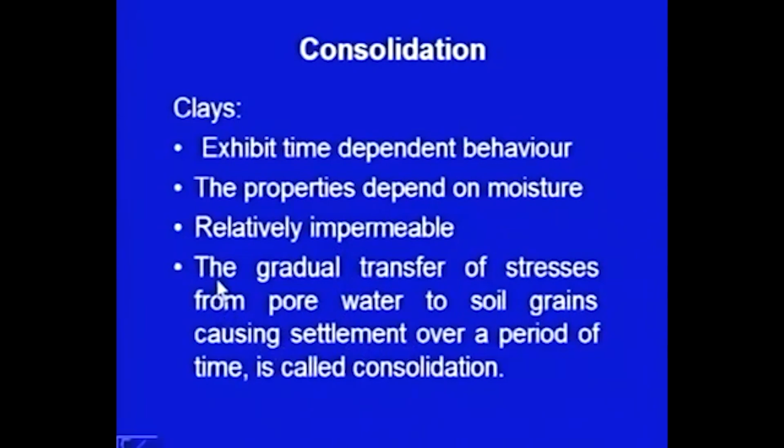And here is one of the definitions. There are several definitions of this term consolidation. This is the concept: the gradual transfer of stresses from pore water to soil grains causing settlement over a period of time is called consolidation. So, let me explain it this way. A building is constructed over a clay stratum.